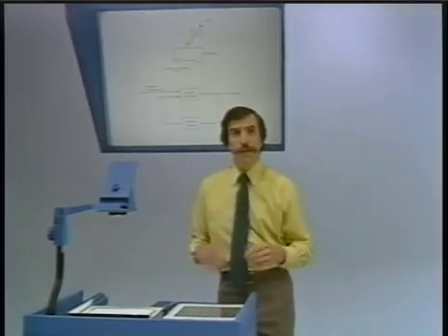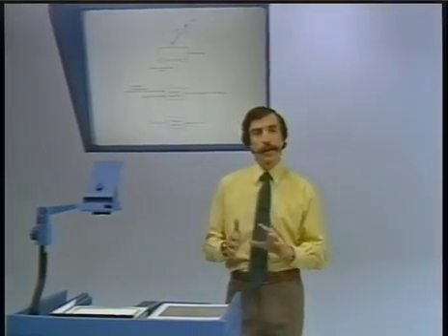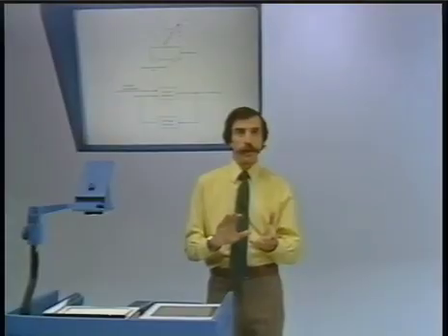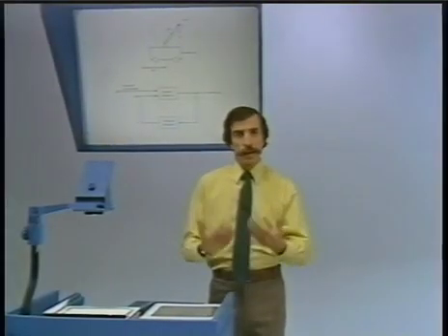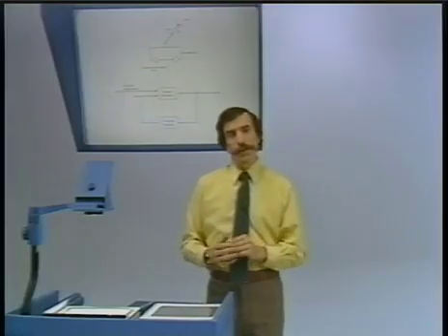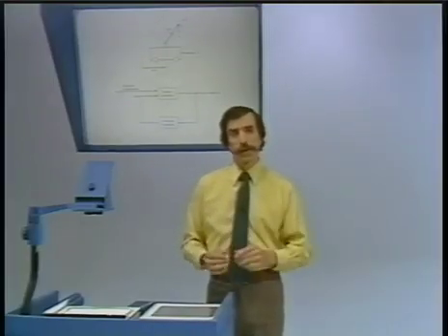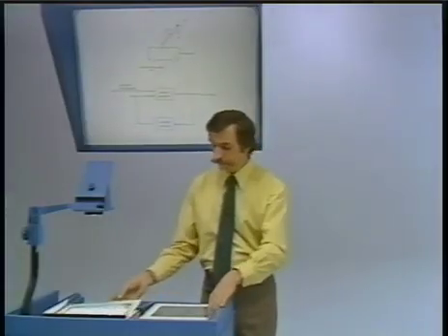Well, as a first step, let's analyze the system in its open loop form. In particular, let's analyze the system without feedback, demonstrate that indeed it is unstable, and then see how we can stabilize it using feedback.